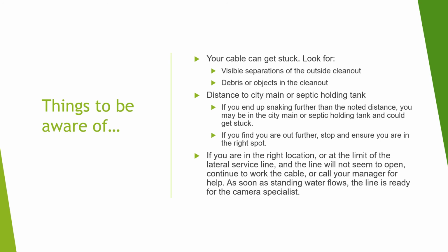If you are in the right location or at the limit of the lateral service line and the line will not seem to open, continue to work the cable or call your manager for help. The typical line should not take more than 45 minutes to an hour to open. As soon as standing water flows, the line is ready for the camera specialist.